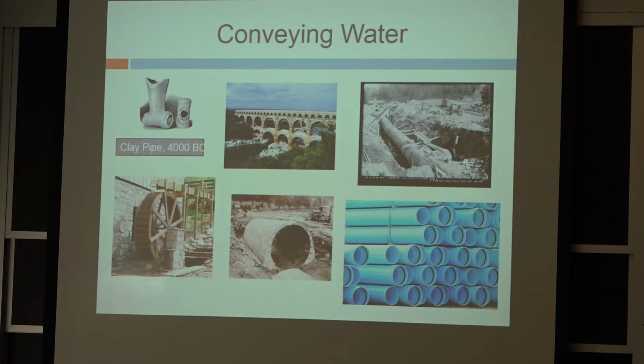So there's a competition between what was in the ground and what you're putting in the ground, and sometimes you have to think about the design. If you're going to switch from a ductile iron pipe to a polymeric pipe, you have to take into account, like I said before, that this is going to be in the ground, so you have to take into account the environment that it's going to operate in. The soil could be acidic, depending on which location in the U.S. you're in, or there could be trace elements from factories in the soil itself. So that's an environmental factor. You also have to take into account corrosion resistance.